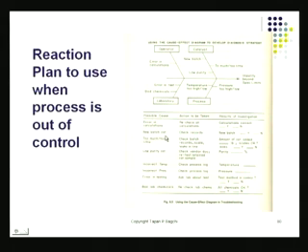New batch of catalyst added, is that true or false? That could have caused the problem. This is also not a problem. That means no, it's not a new batch. Too much quantity added or too little added, check the batch records, check the sheet, look at the scale and so on. Make sure the scale was calibrated, all those things. If that is happening repeatedly, then of course you probably are missing on gauge R and R. That is something you probably should not do. Particularly if you're trying to be a Six Sigma production process, you should not really do that.